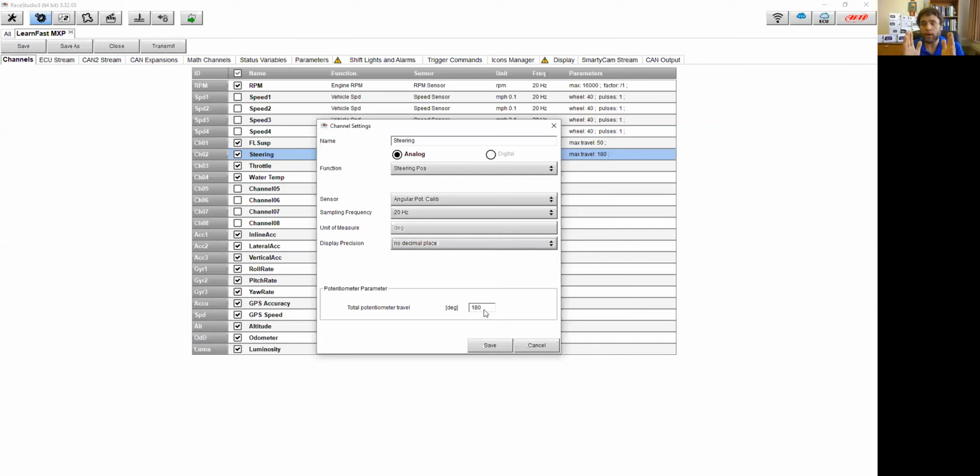So it's one where you pick the appropriate kind of range that you want. So in a car on the racetrack, you're not going to turn the wheel 300 degrees to a side. You might not even turn it 90. I told Roger I usually pick 90. He likes 180, but pick a value so when you go to do it, it gives you a good range that you can duplicate. Don't pick 37 degrees. You're never going to be able to pick 37 as you turn the wheel to calibrate things.